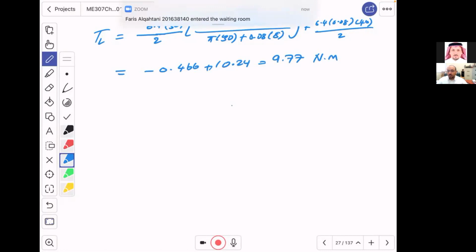However, the collar added enough friction to make the lowering torque positive, and it's actually not a little bit, it became 9.77. So without a collar, we wouldn't have a self-locking mechanism entirely. But you have to remember one thing, that the lowering torque here is 9.77, while the raising torque is 26. So you can see the difference, nearly 3 times.